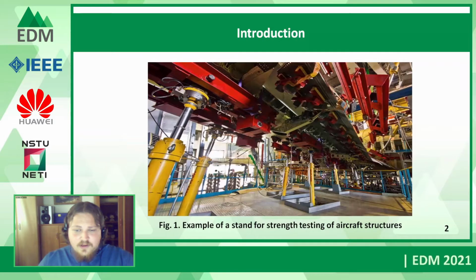The photo clearly shows the structure of the loading system, which consists of a hydraulic servo drive, force sensor, mountings, and a load structure. The loading system reproduces the load experienced by the structure during flight. The reproducible load is most often specified in the form of cyclograms of the sinusoidal load or static load.